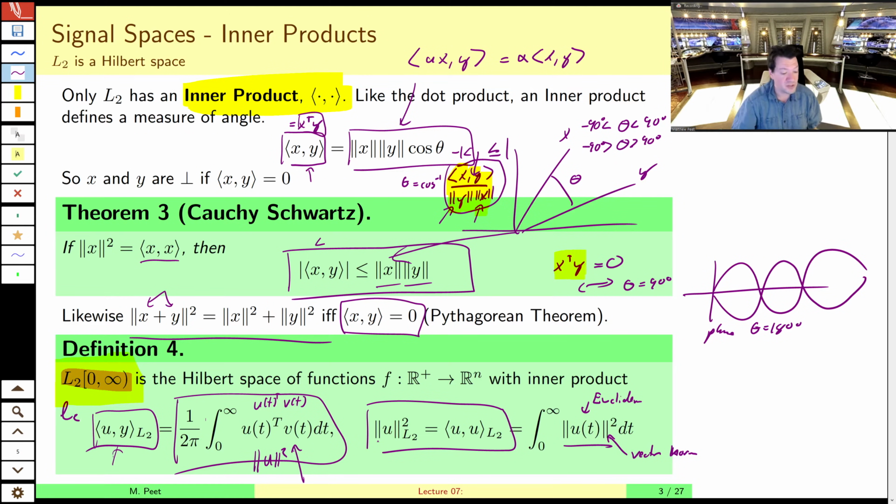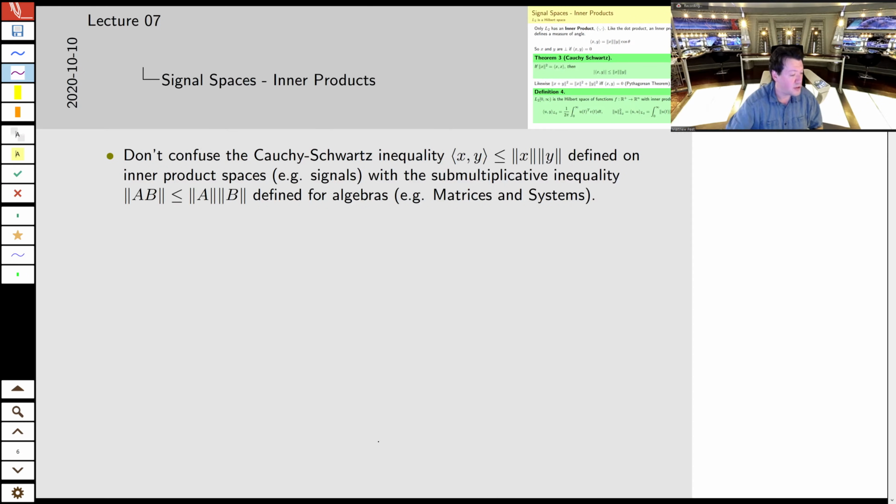And so there is no transfer function if your signals are not in little l2. You can't take the Laplace transform of a signal which is not square integrable. It doesn't make sense, theoretically. Now the Fourier transform is another story, but we're not going to get into that.